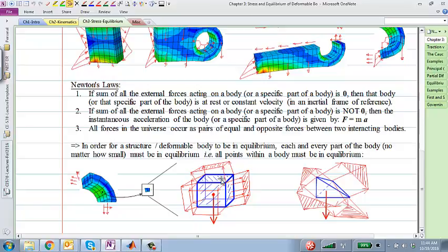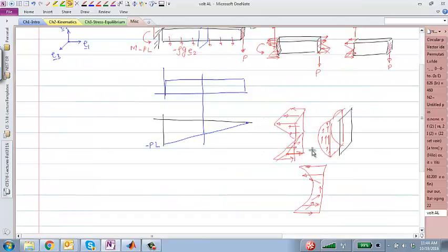So these forces are all distributed forces per area, the way that I have tried to draw them. Another important point is that these distributed forces need not be constant. Do you agree? For example, when we looked at bending, the distributed forces per area that we get due to bending, and due to the shear, are not constant over the entire area. So from point to point, the magnitude and direction of these distributed forces can be changing.